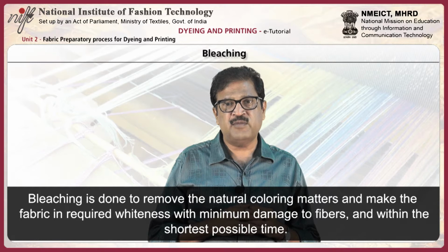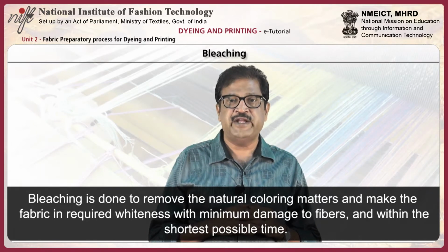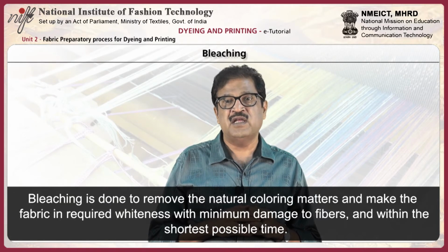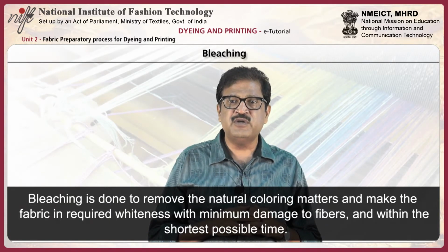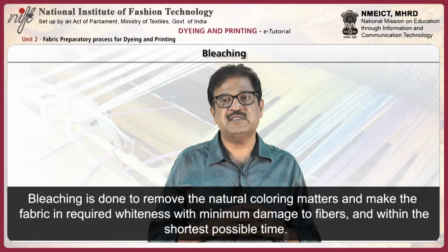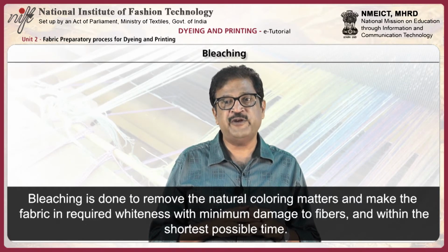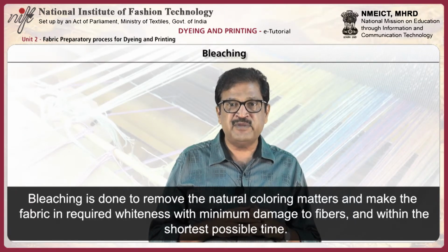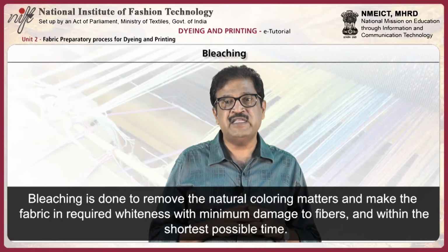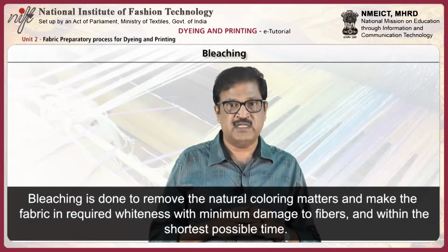Now we will discuss about bleaching process. It is one of the most important processes for textile chemical processing. Bleaching is to remove the natural coloring matters and make the fabric in required whiteness with minimum damage to fibers and within the shortest possible time.